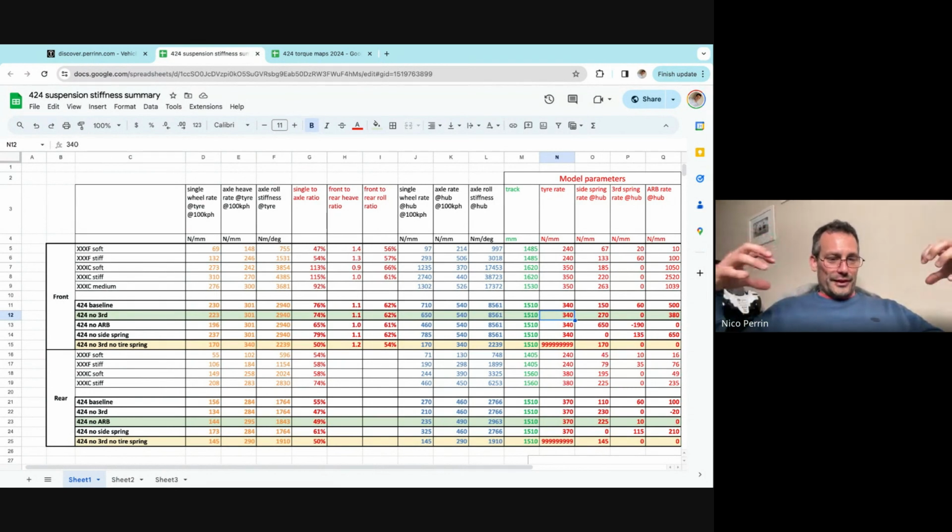Effectively, what links your front and rear suspension is a big spring, which is the chassis, right? And the chassis has got a torsional stiffness. In VPP, in our dynamic simulation, we don't consider it, because we consider that it's so stiff that it doesn't impact the vehicle dynamics. It's not true. In reality, there would be a small effect. But we are working with very big carbon fiber chassis. They have a very high torsional stiffness.